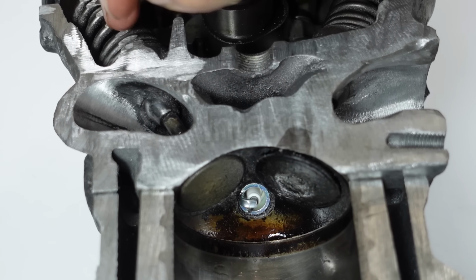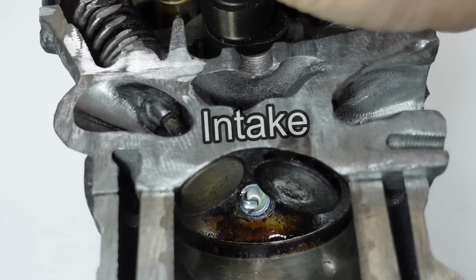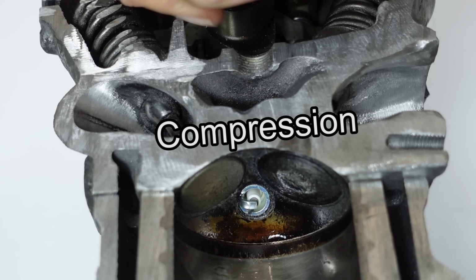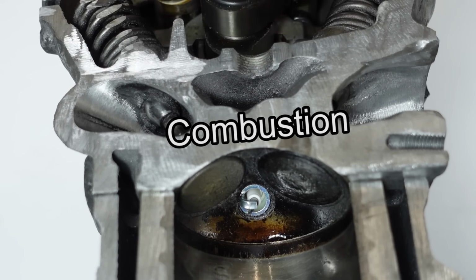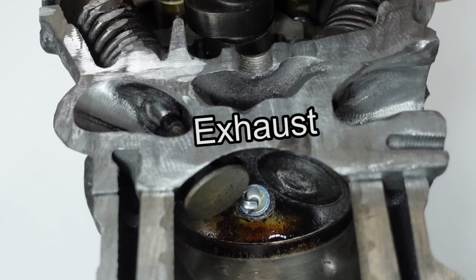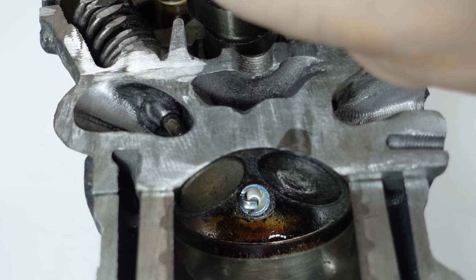The intake valve opens during the intake stroke to allow air and fuel into the cylinder. Both valves are closed during the compression and the combustion stroke to prevent air and fuel as well as combustion energy from escaping the cylinder. And finally, the exhaust valve opens during the exhaust stroke to allow exhaust gases to escape the cylinder.